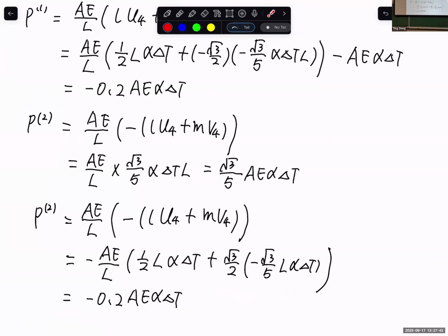So let's say if I want to generate tension, I define this as the positive x direction, so this is node I, this is node J. To generate this tension, I need to apply force at node I in this direction, and I need to apply force at node J in the positive x direction, and at node I in the negative x direction. And we have positive internal force in our element. Everything in our solid mechanics is in equilibrium, so the magnitude of the force at node I, the force at node J, and the internal force are always the same.